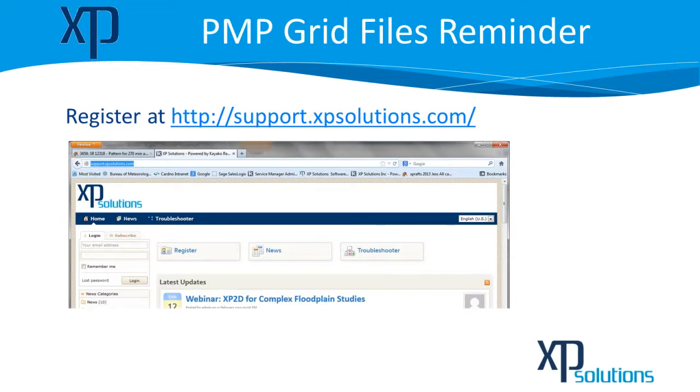Just a reminder as well, we've built a new installer for the probable maximum precipitation grid files, and through training courses and speaking to a few people on technical support, we realized not everyone was completely aware that that function was available. So we have some grid files that go with the probable maximum precipitation that allow some of the variables for the GSAM method to be automatically populated.